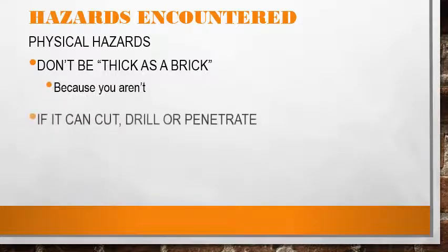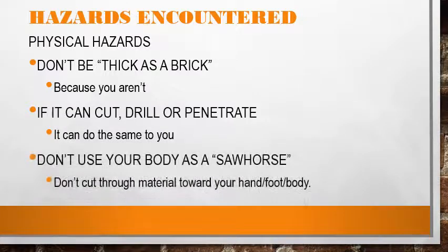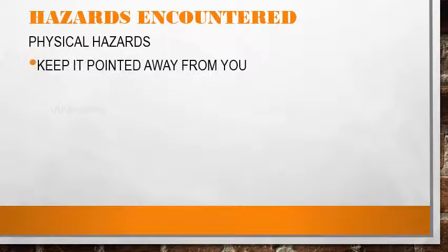Never take a tool and point it towards a part of your body which is holding the object the tool is working on. If the tool can cut through the object, it can cut through the object and then through your hand or your foot or any part of your body. Don't use your body as a sawhorse. Set the object on the ground on a safe place before you use a tool on it.